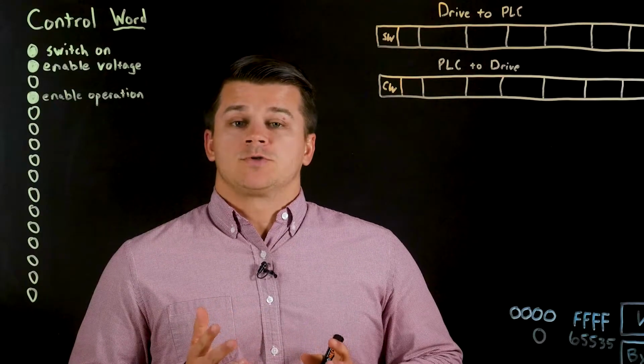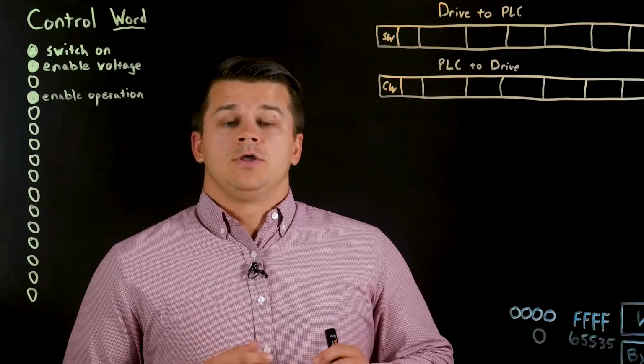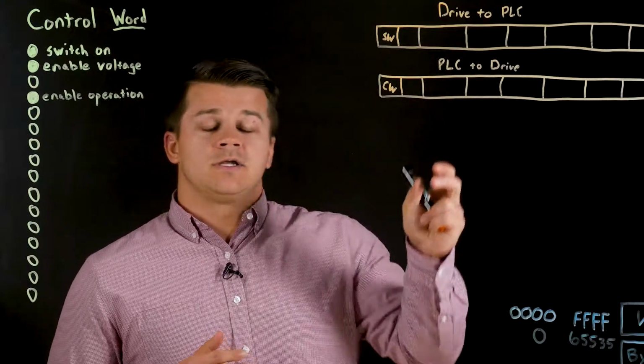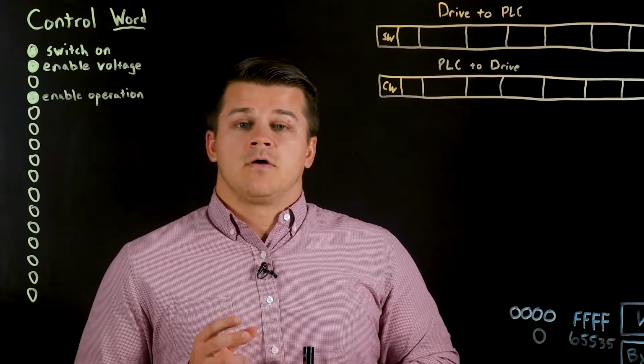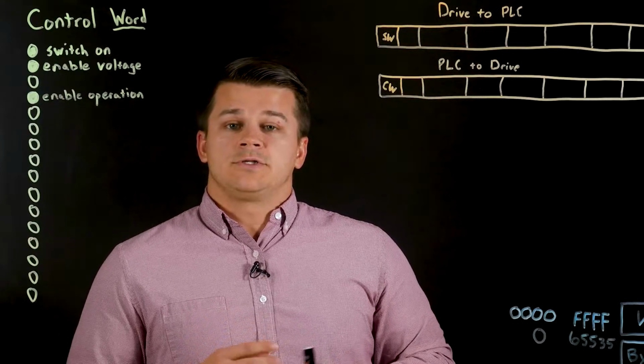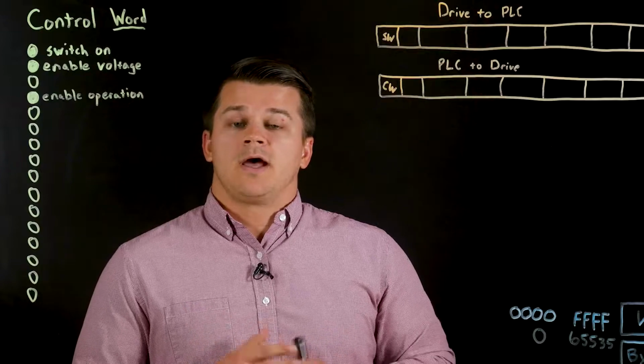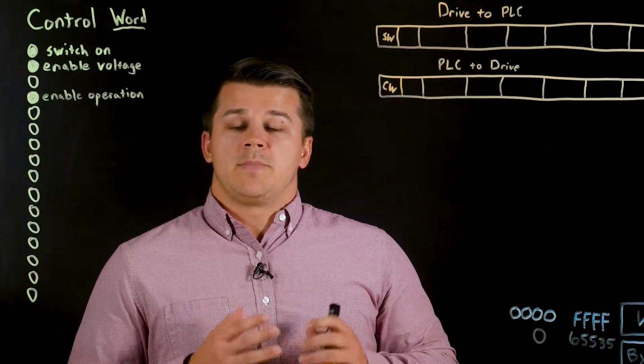When using the Fieldbus wizard in our COMBIVIS 6 software, you can easily drag and drop parameters into this mapping, and the software automatically knows the data length of each parameter, so you can easily check how many objects you have remaining and how many bytes you have remaining in each mapping.